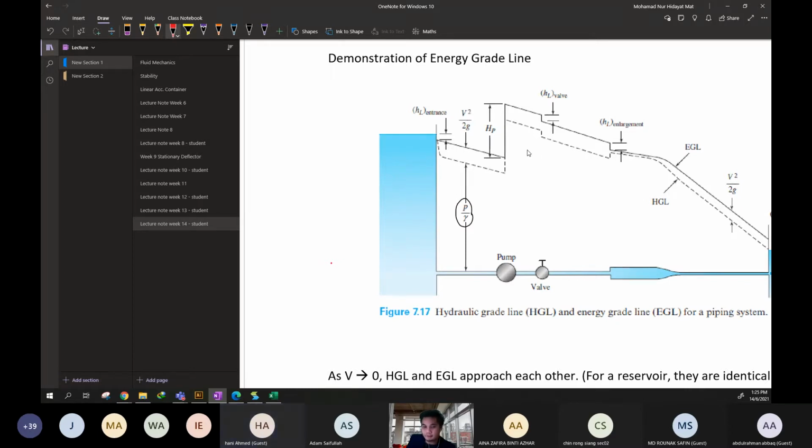Basically, yes, the function of a valve is to regulate the pressure, that means to control the pressure. For this case, it is used to decrease the pressure, because we have the valve to give an obstacle. This is like a resistance. And then there is a slight drop of pressure. And then the pressure reduces linearly due to the major losses, friction along the pipe.